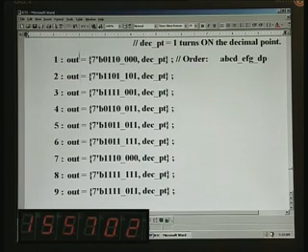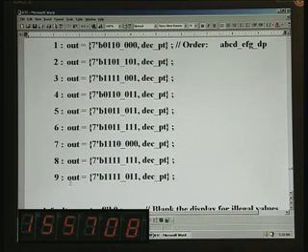So for example, you can just analyze and convince yourself that it is working, and let us take one example. For example, this is 9. What you should have is, it will go like this, and all segments are there except for this segment. So what is this segment? The last center will be G, this will be F, and this will be E. So the E segment must be 0, 0 turns off. So is it A, B, C, D, E, precisely. So you can analyze like this and convince yourself that it really works.